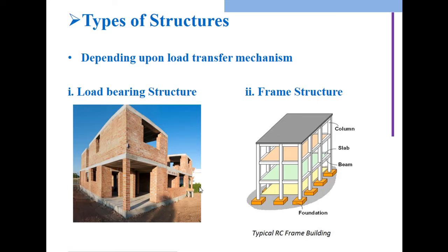Because in STAAD.Pro or in ETABS, whenever you are going to create any sort of project, at that time you need to assign the different kinds of material properties. For that you need to know what a mix design is. Mix design is a very important parameter where we provide the ratio and proportion of the materials, like how much ratio of the fine sand, how much ratio of the coarse sand. Okay, then what is the contribution of the cement in that ratio. Okay, that different ratio depends.